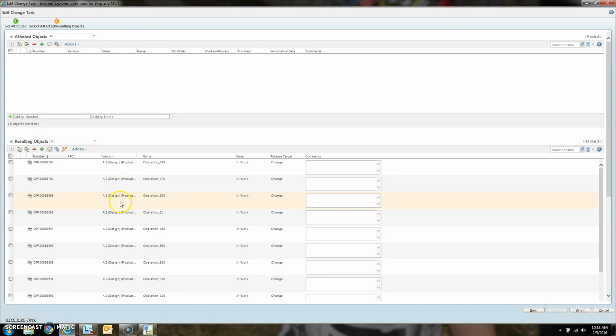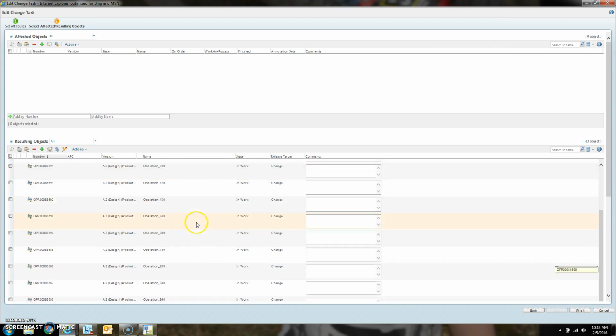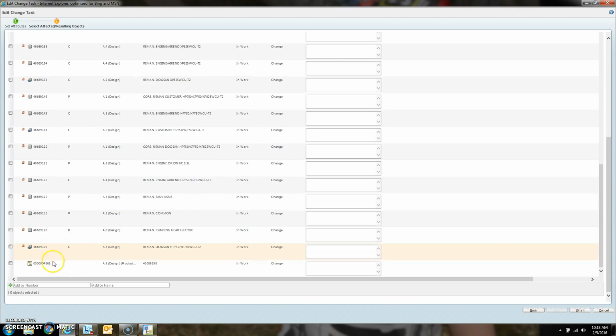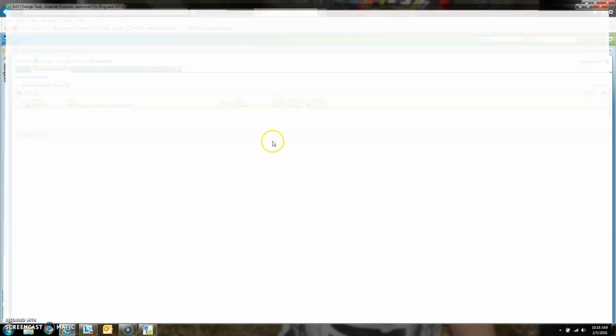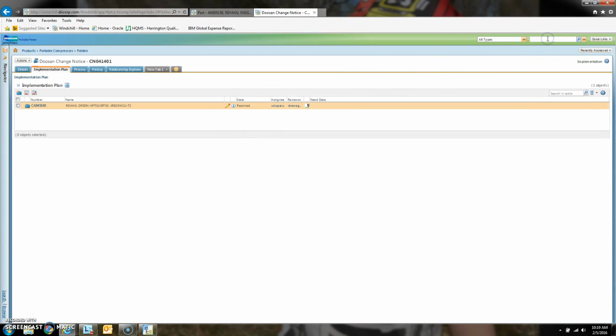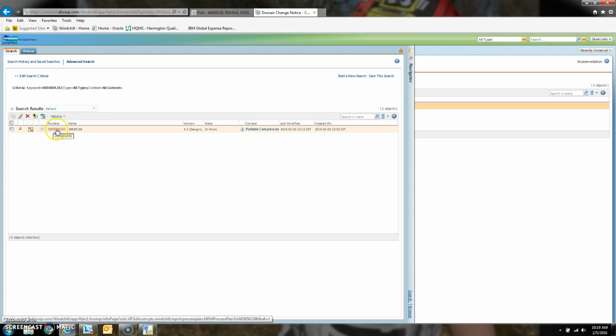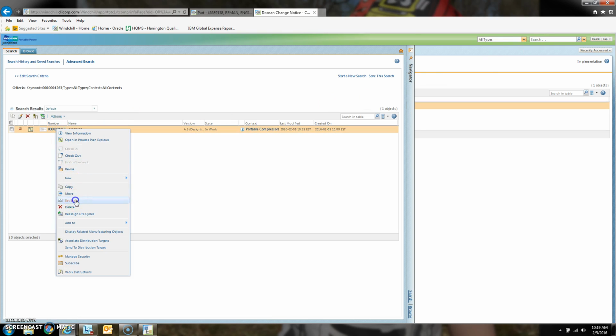Now, last step to finish out this video, if you'll notice all of our operations here are in work. We need to make sure that those are set to release, so we'll do that next. Let's find our process plan. Let's see, right here, let's copy that part number. Control C, now finish in the implementation plan. We'll search for that process plan. We're going to right click, go to set state.